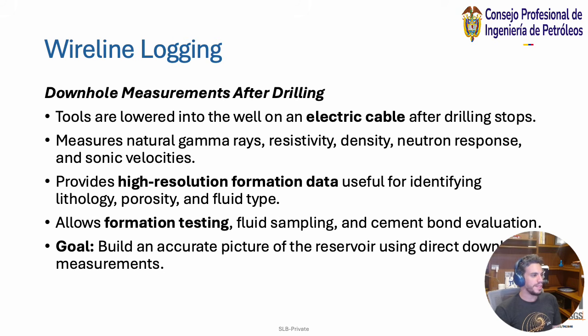Wireline logging is basically downhole measurements after drilling. And why is it called wireline logging? Because you're lowering the tool on an electric cable. So it's an actual wire. There's a big wireline truck with this humongous wire tied to it, and a wireline engineer will attach whatever tool they're going to run and drop it downhole. They run it down. Sometimes you're measuring as you go down, sometimes down and up, and sometimes you run it down and measure as you go up, right?